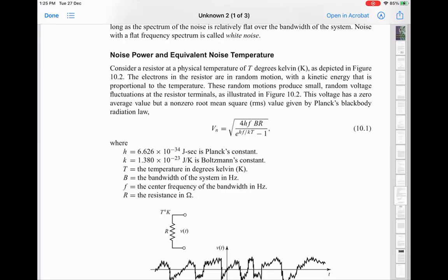So you have to compare these two situations. If I send the signal directly to the detector, I get nothing. So that's basically equivalent to saying I've completely destroyed the signal to noise ratio. I don't get any signal at all. So it goes to 0. But now by adding the amplifier, I've made both the signal and the noise high enough that the detector is able to see it. And the detector's noise now becomes irrelevant because the noise coming from this process itself is much, much higher than the noise of the detector. That's usually the condition in which you want to operate.